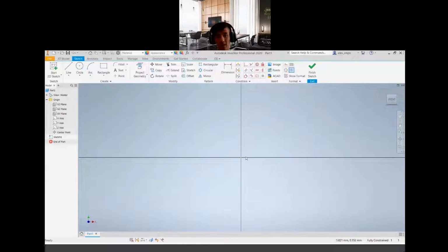Okay. So what I would like you to do is you go to rectangle. The first starting point, each and every time when you create your geometry, it's the best you utilize the origin. So you just go to rectangle, first point, snap to the origin here, please. 0, 0, 0.